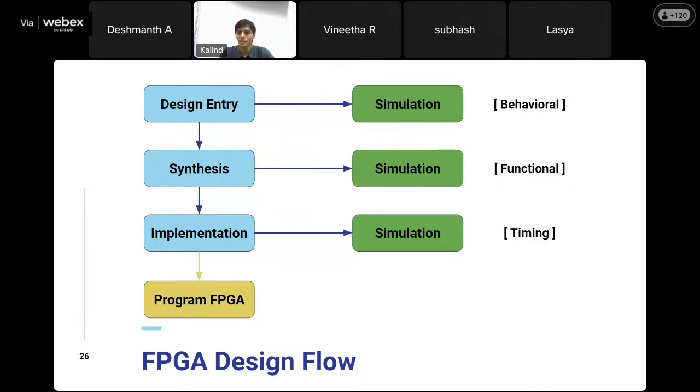There should not be much delay as well. If there is a longer propagation delay in your design, then it's not called a good design. So that's how you do it. You have the timing simulation at the very end, because that's where your design is actually implemented inside the CLBs, or basically inside the LUTs, right? So this is a basic abstraction of how the FPGA design flow is.